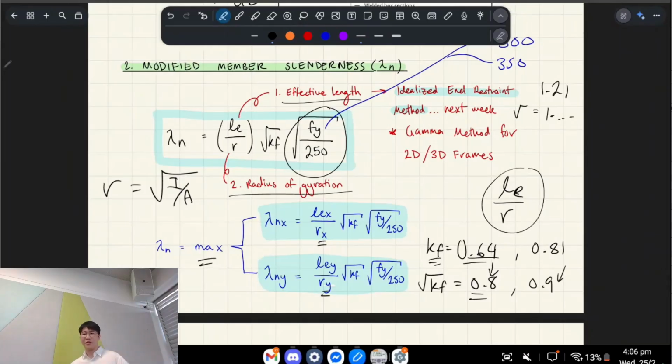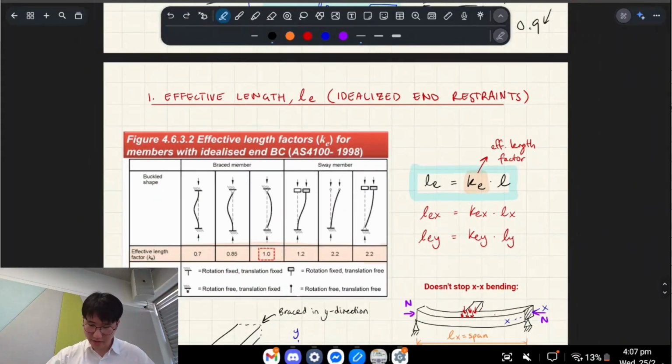So if we get a shape that has a really unbalanced slenderness ratio, you know that it's going to buckle in the Y direction, the YY direction, or the minor axis. However, if we put enough restraints on it to change its effective length, it becomes a different story. So it's the ratio between the effective length and the inherent shape's radius of gyration in the x direction and the y direction. I'll show you what that looks like in the next slide.